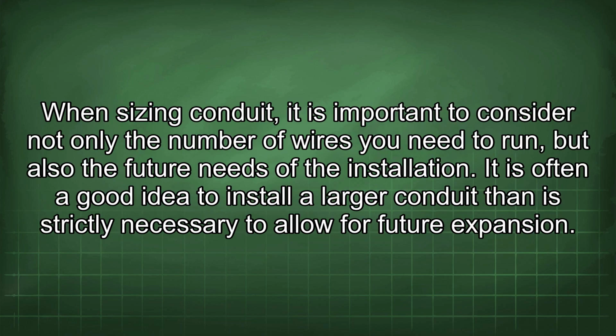When sizing conduit, it is important to consider not only the number of wires you need to run, but also the future needs of the installation. It is often a good idea to install a larger conduit than is strictly necessary to allow for future expansion.